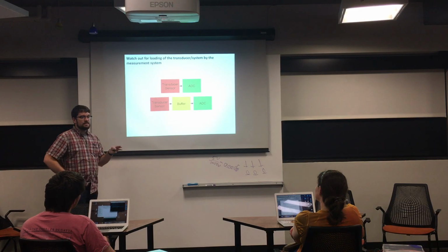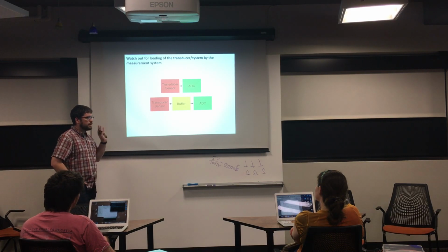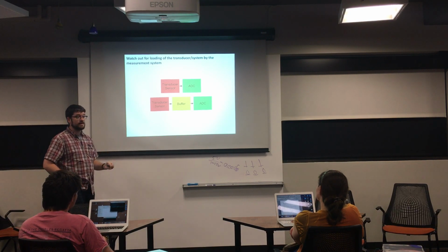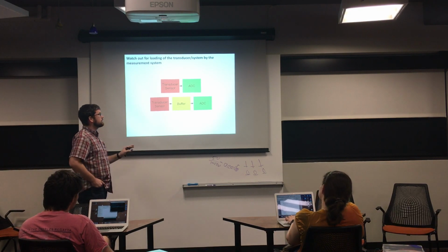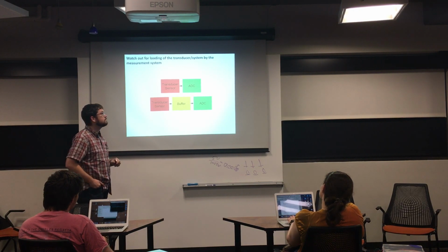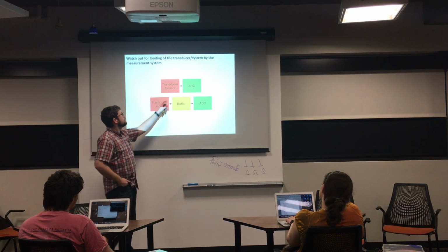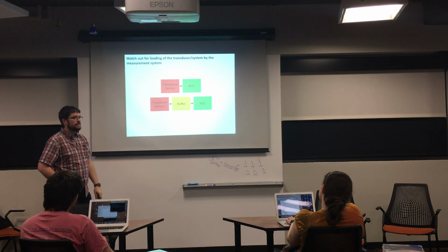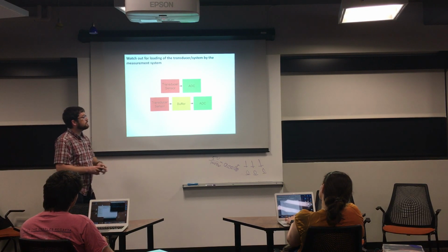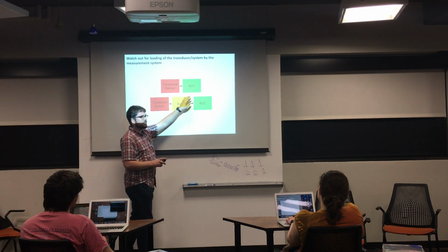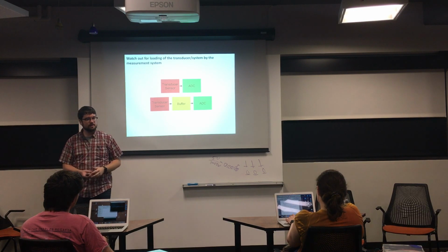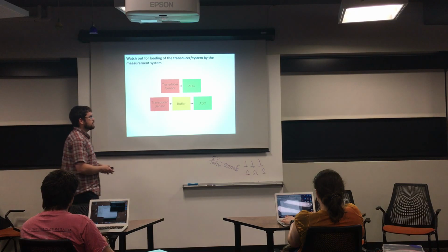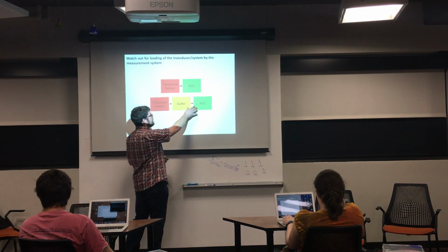Another gotcha, and this happens very often, I would say, in research labs, and folks don't realize what's happening and why it's happening. And it can really mess with your calibrations and make your data virtually invalid. A lot of times people hook up the transducer, the sensor directly to the analog to digital converter, and that's it. And sometimes that's fine. If your analog to digital converter has what's called very high input impedance, which is something that we'll talk about later, you're probably fine.